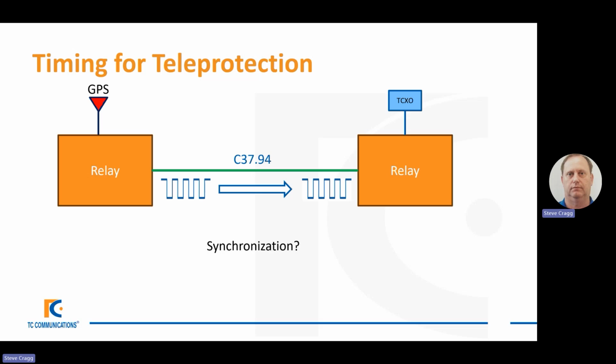So that's an additional benefit that you can have here. And so in the times where they wanted one central real-time clock on the relay on the left, and they wanted to synchronize these two, it is possible to use the C37.94 and the really accurate level of that clock signal to synchronize those two relays together.